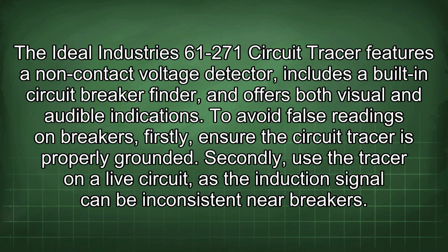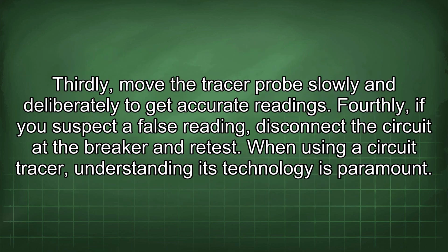indications. To avoid false readings on breakers, firstly, ensure the circuit tracer is properly grounded. Secondly, use the tracer on a live circuit, as the induction signal can be inconsistent near breakers. Thirdly, move the tracer probe slowly and deliberately to get accurate readings. Fourthly, if you suspect a false reading, disconnect the circuit at the breaker and retest.